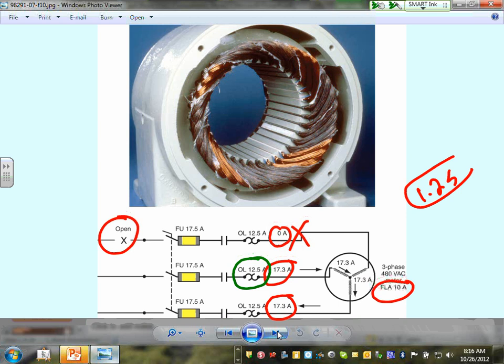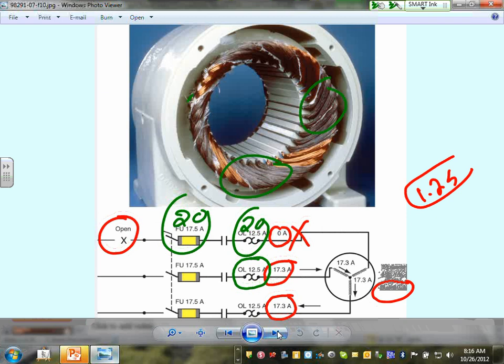Now, here's where you can tamper with that. If you put this in a 20 amp, and all these are 20 amp, now, do you think your motor is fully protected? No. Now, do you guys understand why? Do you guys understand why the overload protection device of motors is very important? Because you don't want to be looking at multiple phases burn. Phases burn. Okay. Any comments?